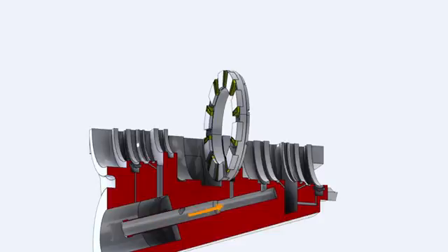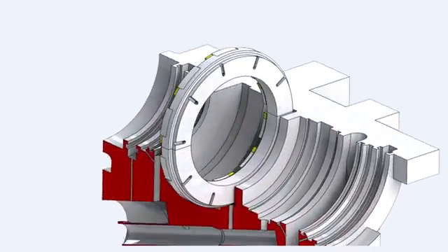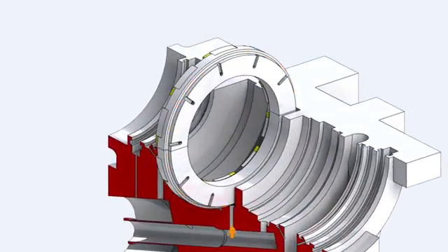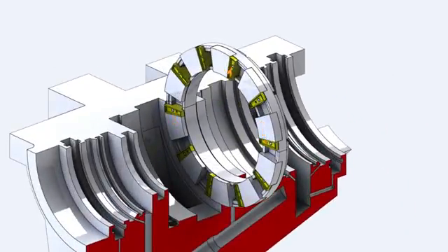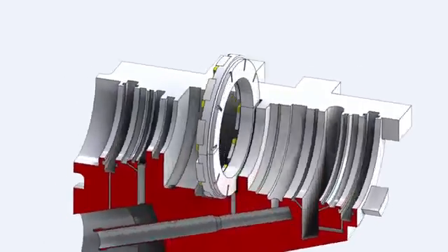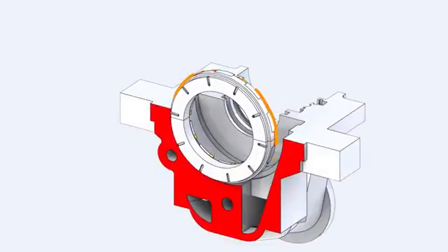For lubrication, oil is supplied through the oil feed pipe to a port in the lower bearing housing, where the oil flows into the annular space around the base ring. Then, oil flows through holes on the back side of the base ring to the oil control plates, which introduce the oil directly to the bearing surface before each of the pads. Oil exits at the pad's periphery to the thrust bearing drain cavity to the lube oil drain piping.